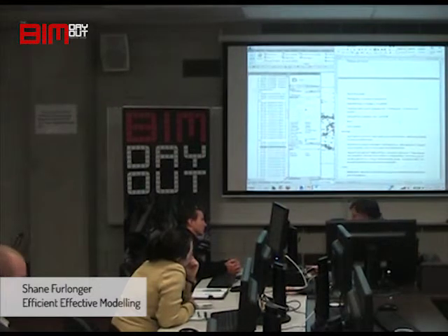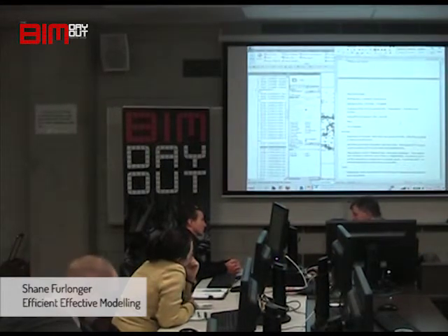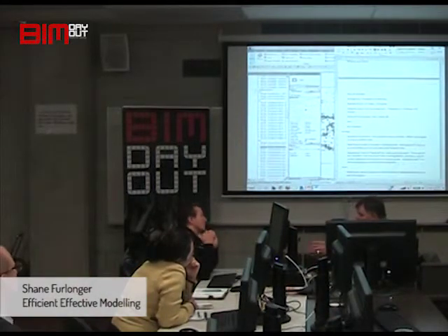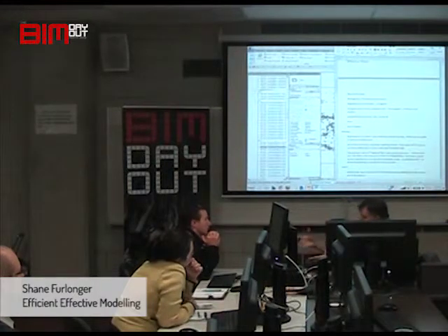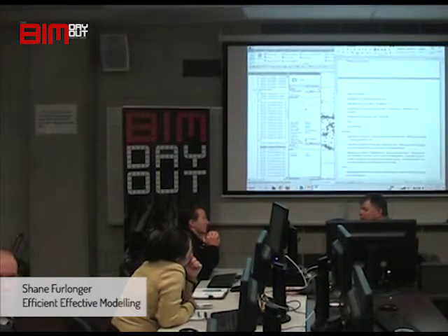And you can put windows in your curtain wall. So let's say I put that in somewhere, one of the panels of the curtain. And that becomes a window, and I can adjust the height, up and down, sideways, whatever, without having to edit a panel.